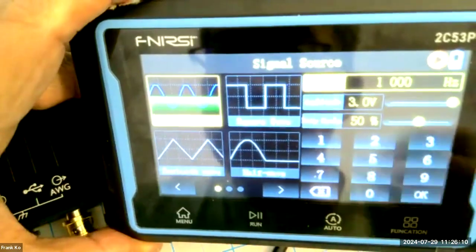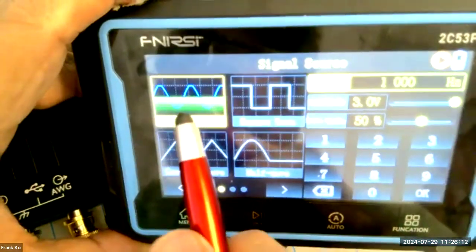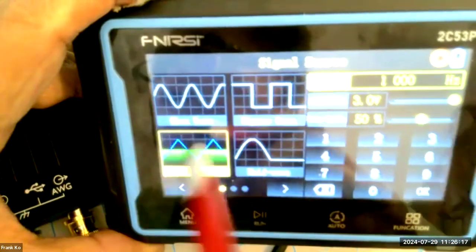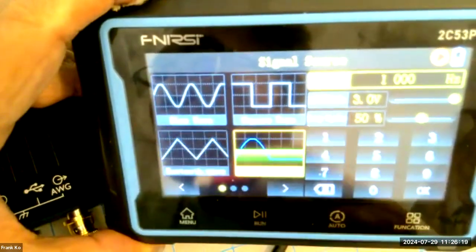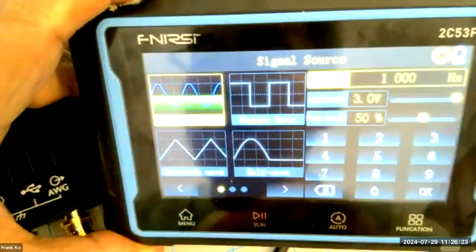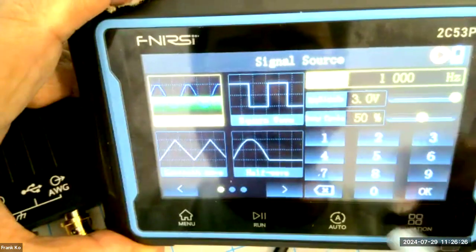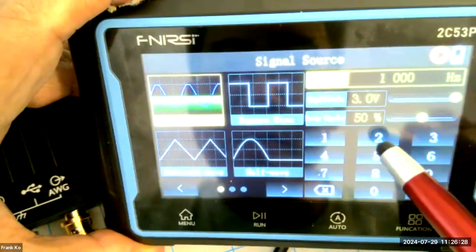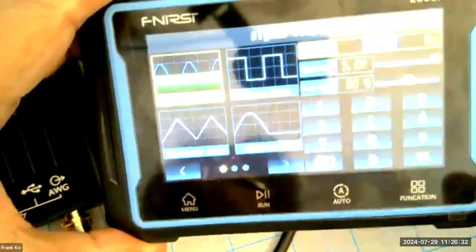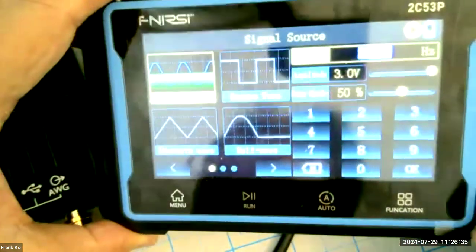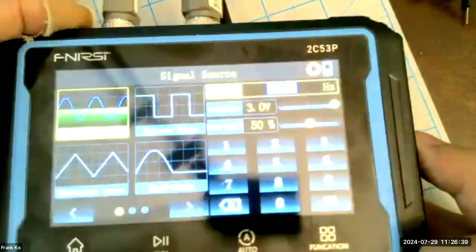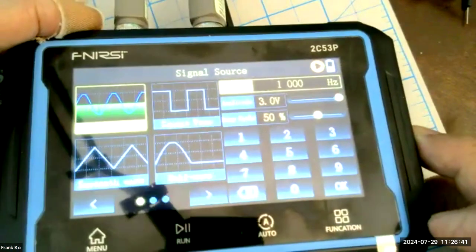And this gives me my signal source controls. My signal source controls allow me to select any of a number of, like, 12 different waveforms: sine wave here, square wave here, sawtooth, triangle, half wave. Okay, we want sine wave, so we select sine wave. The frequency is displayed here. So if I wanted 2,500, that's now 2.5. Can't read the number, I apologize. It's really hard with this amount of glare in the room. I apologize. Oh, there you go.